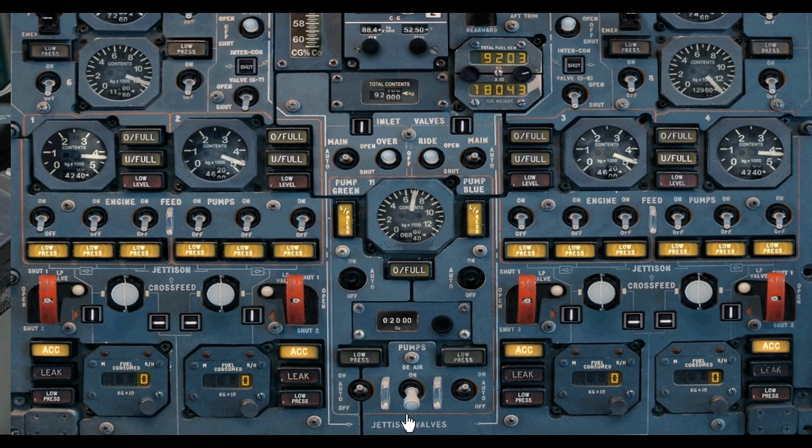And then our engine feed pumps, there are 3 pumps for each engine. There's a main pump and 2 auxiliary pumps. We need to turn the main pump on tank 1 on, the main pump on tank 2. We leave, just trying to get the pop-up to show, but it's not. So the main pump is on tanks 3 and tank 4.